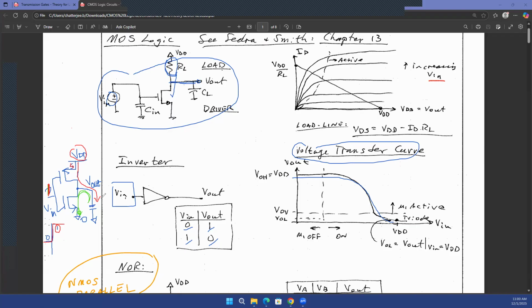And only if there is switching going on, that switching you can assume as AC current, right? It may not be a sinusoidal current, but it's still a switching going on which is alternating. It's not DC, it's not fixed. And as soon as there is some amount of switching going on, the capacitor can charge or discharge. The capacitor charges through the PMOS and the capacitor discharges through the NMOS.